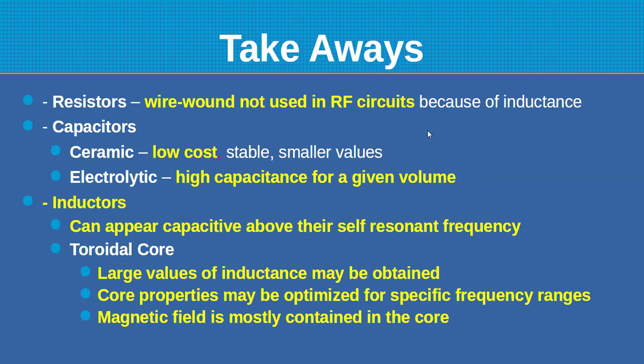So the basic takeaways: we don't use wire wound resistors in RF circuits because of the inductance. We use them in audio frequency or power circuits. And as far as capacitors, the ceramic are low cost, stable values. The electrolytics give you a high capacitance for a given volume.